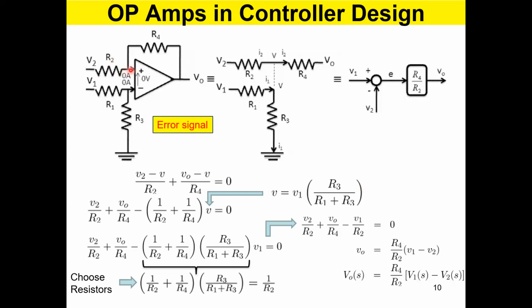You can see the same point here, right? Both terminals have pretty much the same voltage. So let's call it V and V. You have to put a value there, because we don't know it. You can't say it's 0. Some voltage V. And using that voltage, you write down the KCL for this node here.